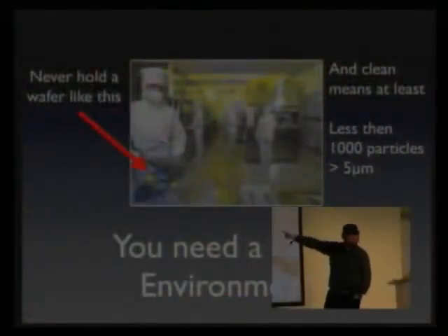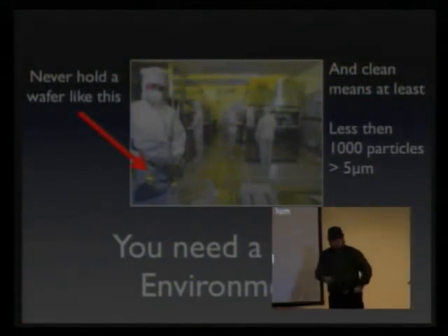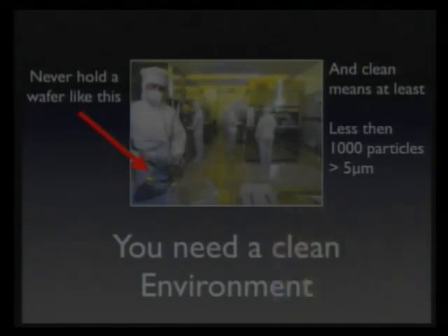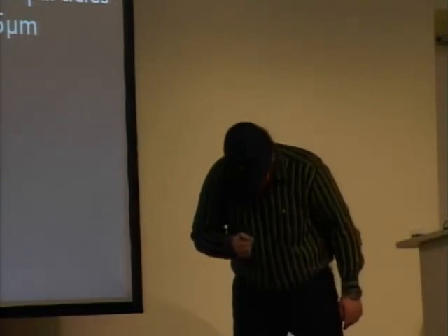Why should you never hold a wafer like this? Because you can get contamination from the top. If you hold it that way, it's much harder to get particles on it. So when you check your wafer, you check it that way, not that way. Especially when you're wearing a beard. Big problem. And smoking.